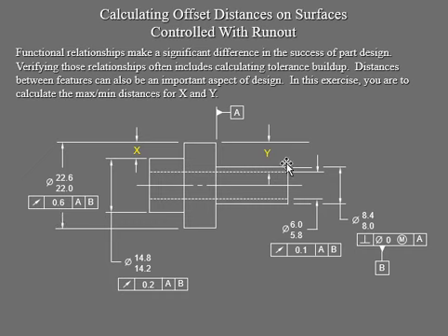This diameter here is controlled by this perpendicularity, and this one is another runout, which is this little diameter right in there, controlled by 0.1. So the corresponding control frame shows you which diameter or circle it is controlling.